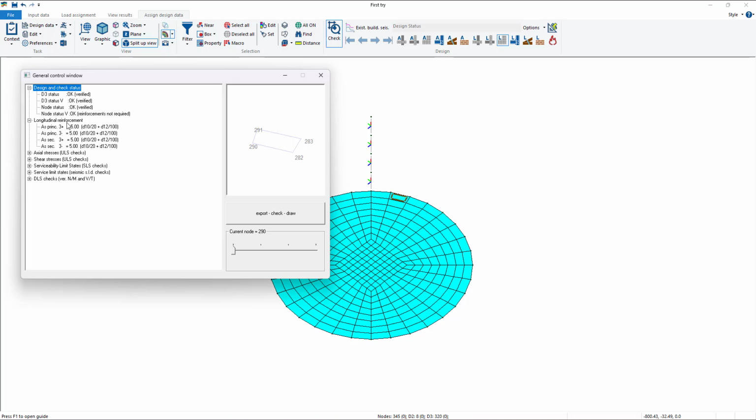for each direction, for the lower, from the bottom layer of rebars, the software used diameter 10 with spacing 20 centimeters, and then it added the D12 rebars with 100 of spacing. The spacing of the additional rebars is calculated by the software just to reach the verified status.